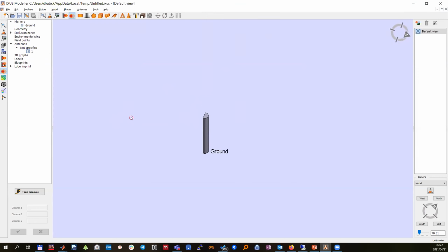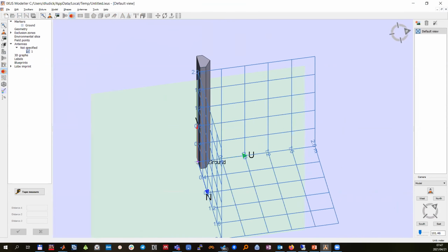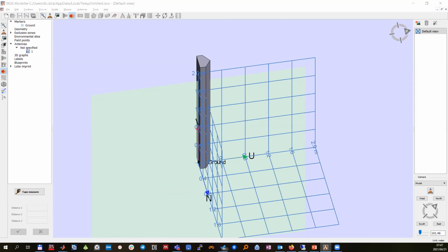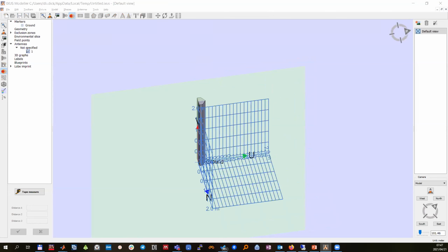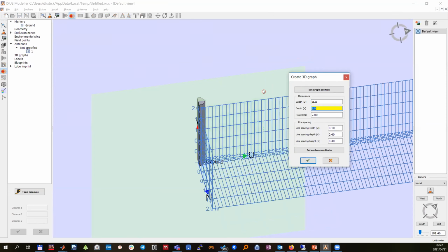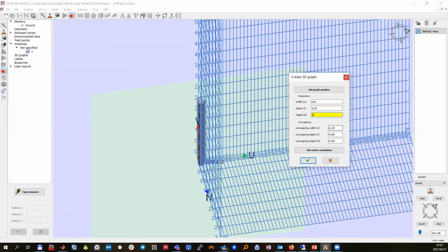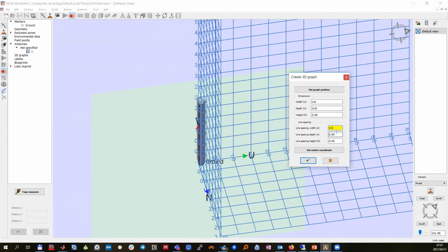Okay, so first thing is, for those that have not seen, in terms of dimensioning, we've also added a bit more functionality. So we've actually added this three-dimensional grid, which can be used to dimension things a bit nicer in IXUS. So you can set its width, you can set its depth. Now these are all things that I calculated a bit beforehand, because I sort of looked at the compliance zones. But obviously you can adjust this after you've simulated your antennas or multiple transmitters or geometries and so on. The grid's fairly versatile.